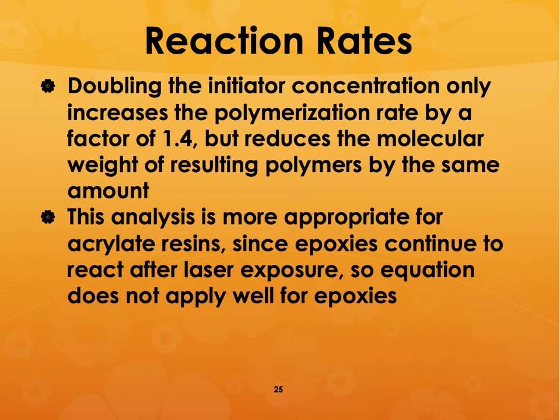If you increase the initiator, it can increase the polymerization rate by a factor of 1.4, but it reduces the molecular weight of the resulting polymers by the same amount. Now, this is more appropriate for acrylate resins, so it may not always work well in the presence of epoxies.